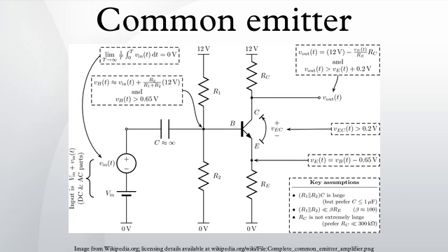Bandwidth: the bandwidth of the common emitter amplifier tends to be low due to high capacitance resulting from the Miller effect. The parasitic base collector capacitance appears like a larger parasitic capacitor from the base to ground. This large capacitor greatly decreases the bandwidth of the amplifier as it makes the time constant of the parasitic input RC filter large, whereas the output impedance of the signal source is connected to the ideal base.